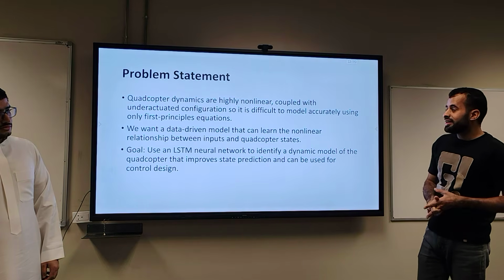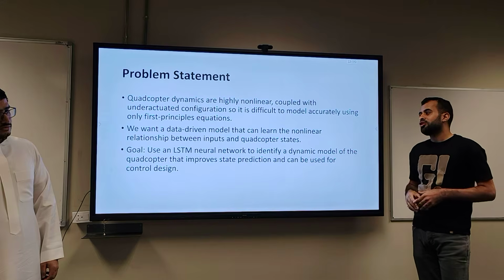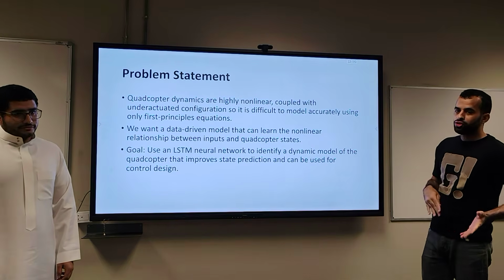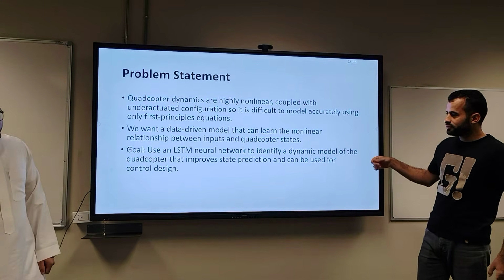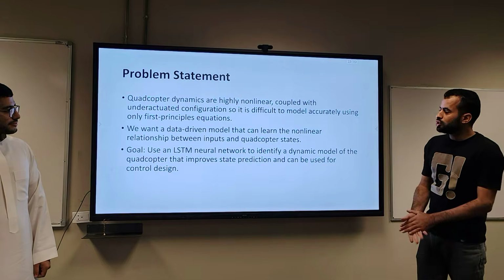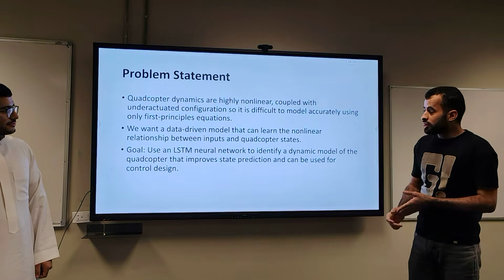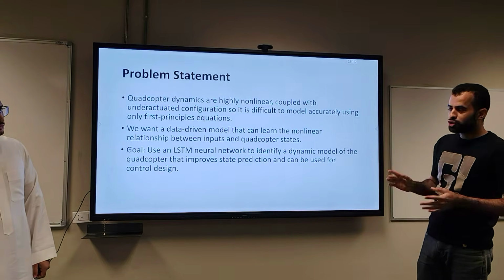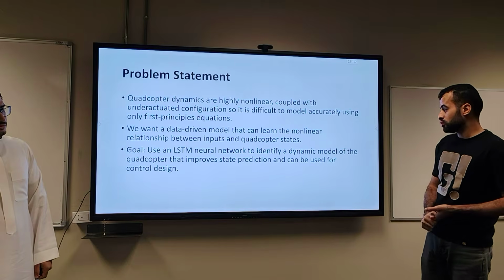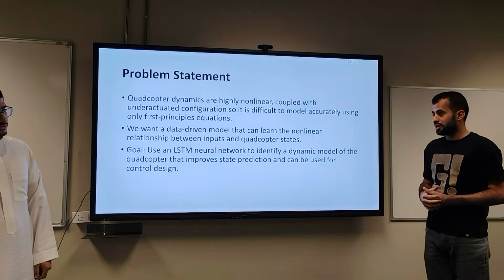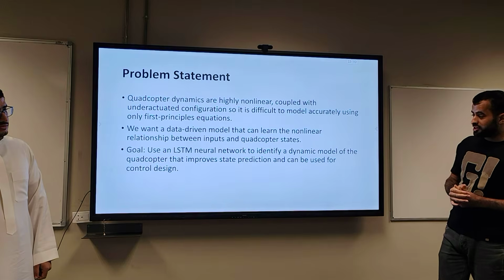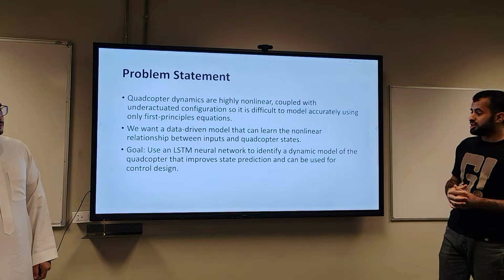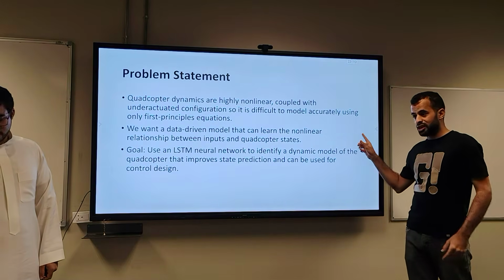We want a data-driven model that can learn the nonlinear relationship between the input and the output of the quadcopter. So our goal is to use LSTM, long short-term memory neural networks, to identify the dynamics of the quadcopter, to improve state prediction and to be used for control design.